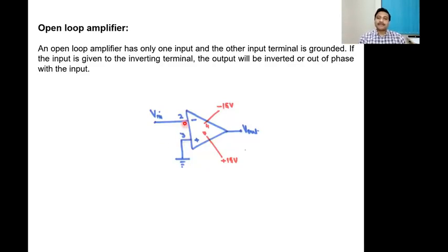So I'll keep writing these terminal pin numbers just to clarify that these are the pins at which, in a real circuit, you are supposed to provide the signals and make the measurements from. So for the 741, pin number 2 is the inverting input, pin number 3 is the non-inverting input.